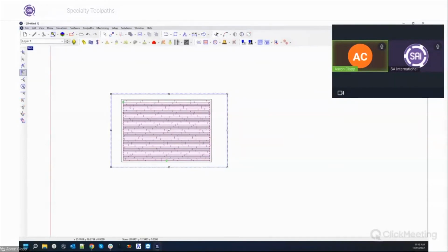You may still run into a little bit of that, but depending on the material, the amount of time that you would save cutting it like that versus cutting in 3D would be so much more that you could just sand it or even run it at like 90% overlap. I mean, at that point, you're almost doing the same thing as a 3D. But if you're doing it like 60, 70% overlap, you're probably saving yourself a lot of time versus doing it as a slant.